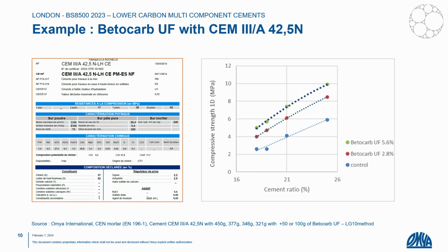Other question, can I use the calcium carbonate of ultra high fineness to wake up my binder in winter time? That can be a question. That's why, for example, such ultrafine ground calcium carbonate are used in tile adhesive as a substitute of calcium formiate.